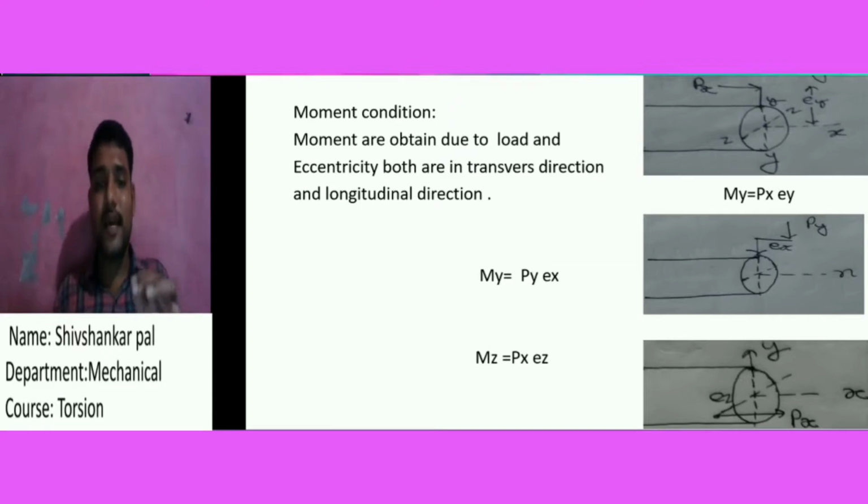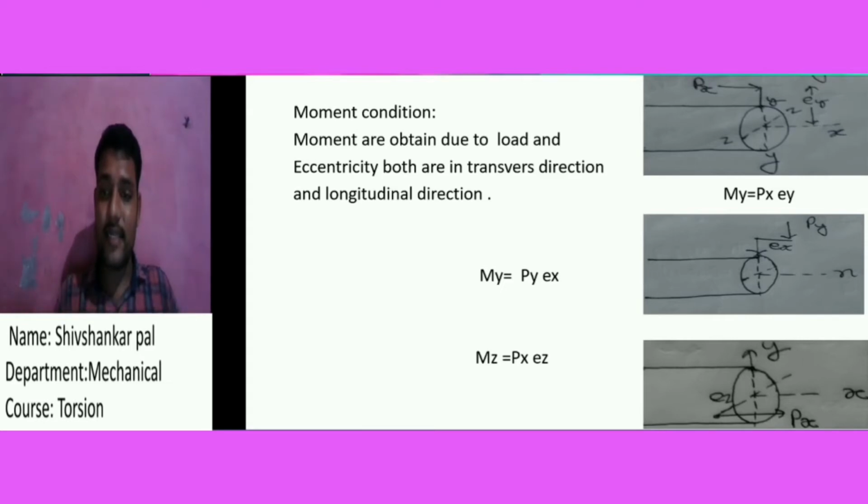That moment is not considered a torque; it is considered a moment, because the load is in the longitudinal direction and the eccentricity is in the transverse direction. In the second diagram, the load is applied in the transverse direction and the eccentricity ex is in the x direction, producing the moment about y, Py × ex. That is considered a moment, not a torque, because one is in the transverse direction and the other in the longitudinal direction.